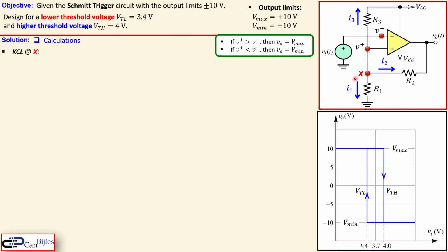So at this node X, I can say these three currents must add up to 0. That is Kirchhoff's current law in the general form. Now we need to use Ohm's law to write these currents as volts over the resistors. What you see here is that the voltage Vx over the resistor R1 is effectively also I1.